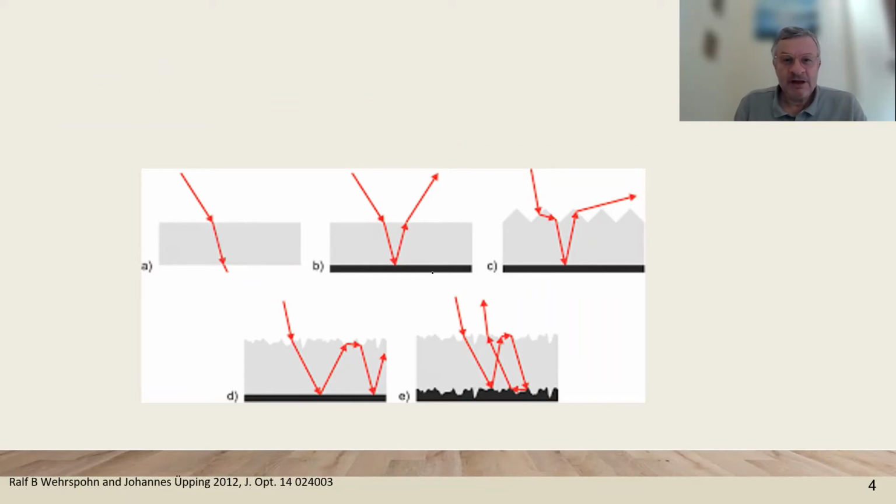Therefore, a simple back mirror multiplies by 2 the pathway of the light, but still this is going out of the solar cell, so that we use schemes for randomizing the reflection, and then this increases notably the pathway of the light, and then the probability that the photon is converted into an electron-hole pair of carriers.